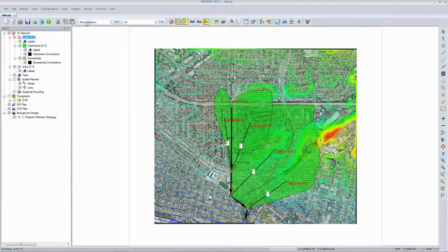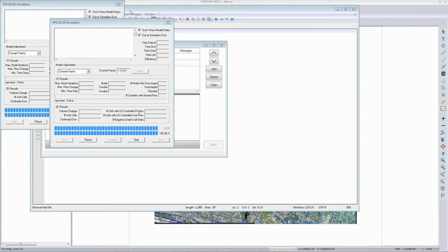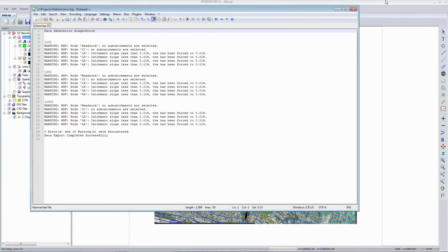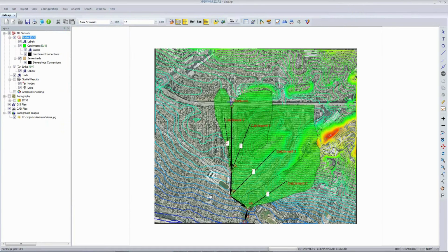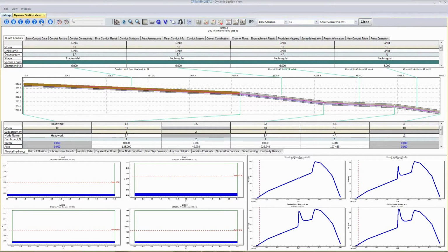So let's just do that now. Choose the solve manager, solve all of these at once. I have an 8-core computer, so I could do 8 of them all at one time. I'll close these dialogues, come back, show you the hydraulic results, and then I'll get Nicole to tell me what the time was to be able to get to this point where I'm showing hydrology and hydraulic results in a stormwater model. All right, Nicole, what was my time?